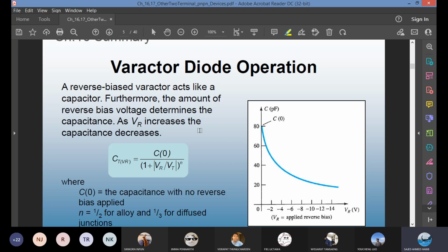So the depletion region is void of conduction carriers. There is no conduction in the depletion region. It sounds exactly like a capacitor with two plates. In the middle, you have an insulating material known as dielectric. You also know that the two different materials have different polarities. So when it is reverse biased, you will see a capacitance at the p-n junction of the diode.